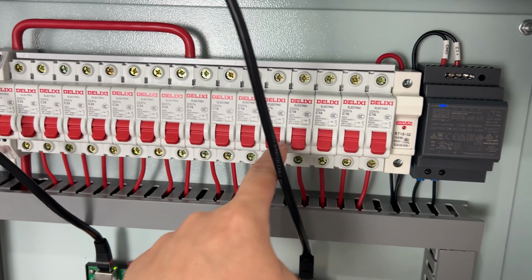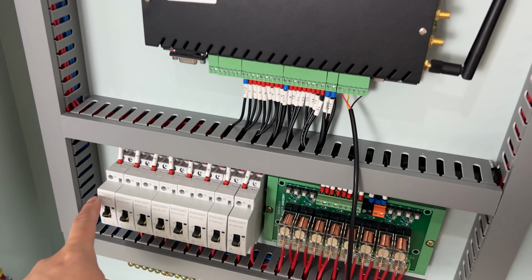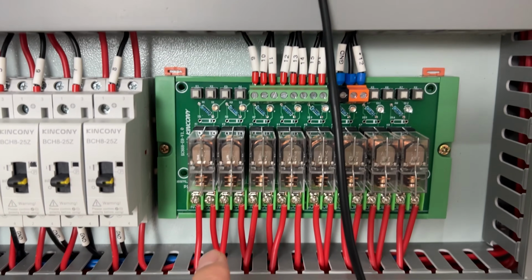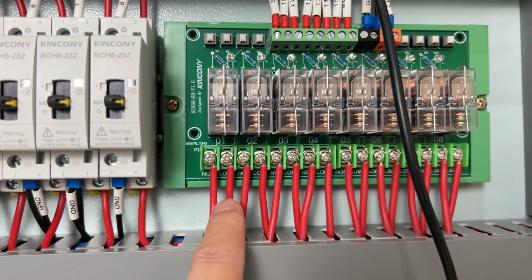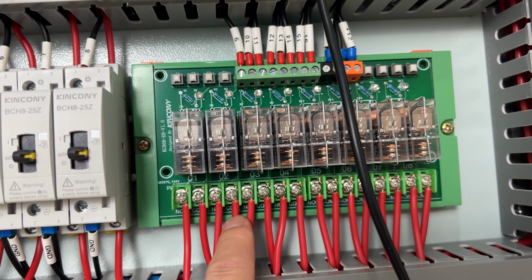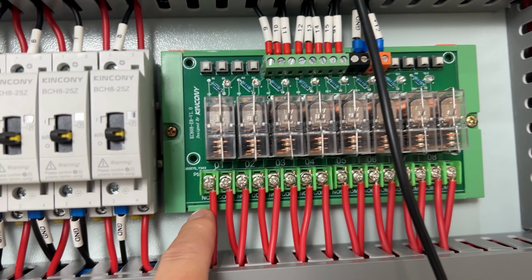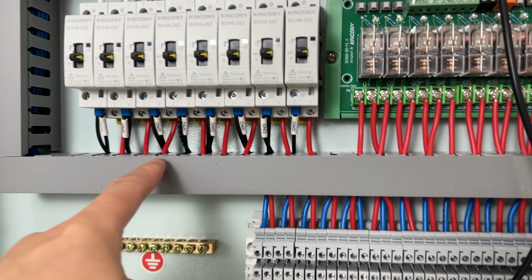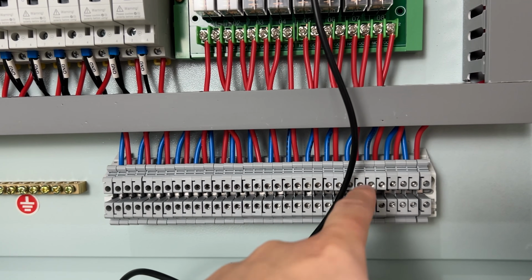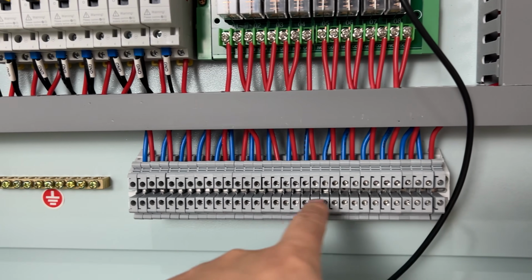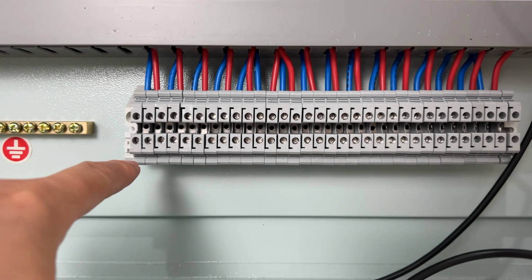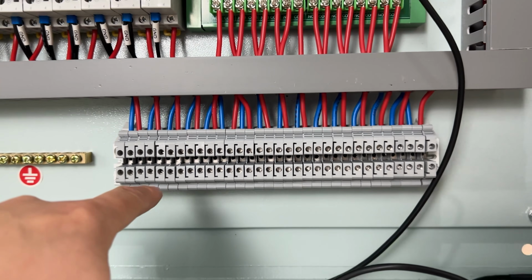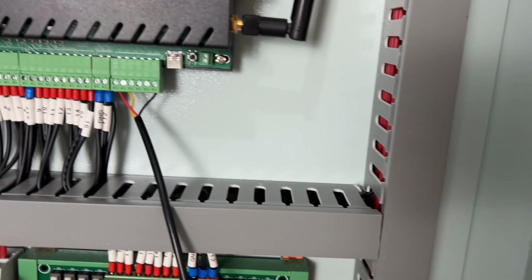So every channel, of the 16 channels, is connected with a contactor and an external relay. You can see this external relay. That is for the COM, this COM, this COM, and this normal open. That normal open has output, and the contactor is output. So it goes to this terminal. At this terminal, you can connect your load, maybe your lamp, your curtain or your motor. Just connect it here.